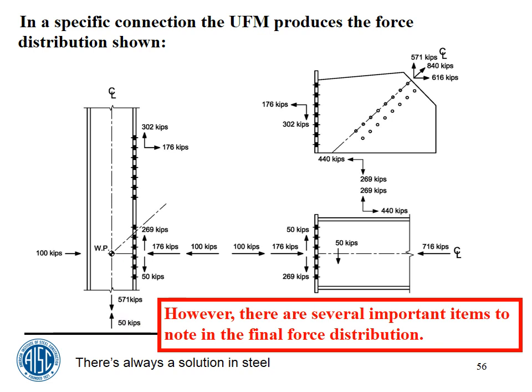On this one you see a red arrow. I can't see it because it's behind some stuff here. And there's nothing else. That piece that you see here of the column is in equilibrium under those forces. The gusset is in equilibrium under this force. The piece of the beam that you see here is in equilibrium under this force. So, that's one thing that I wanted to point out.